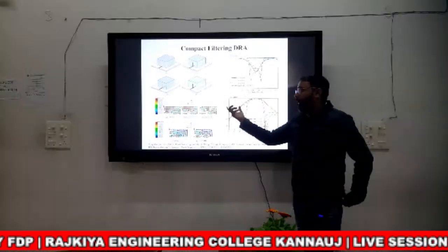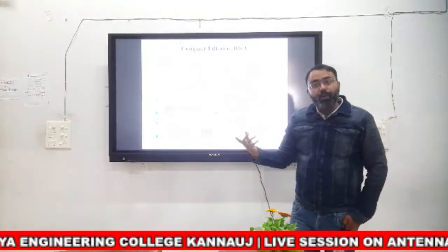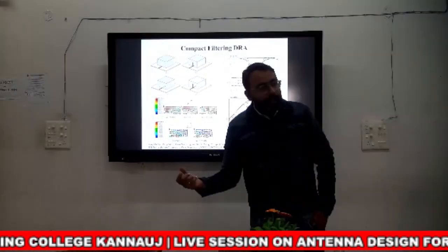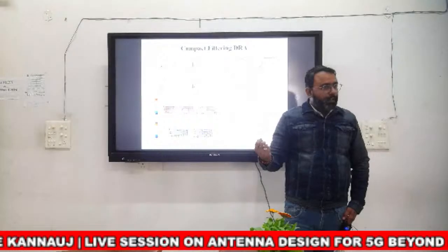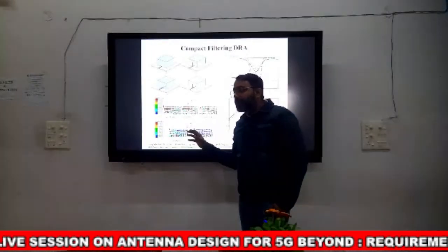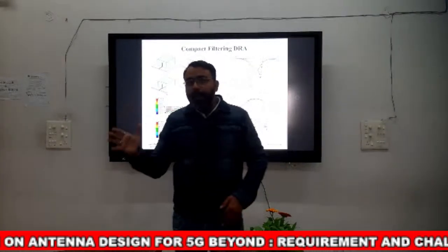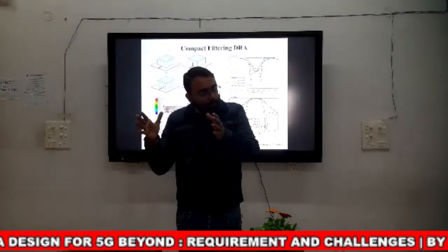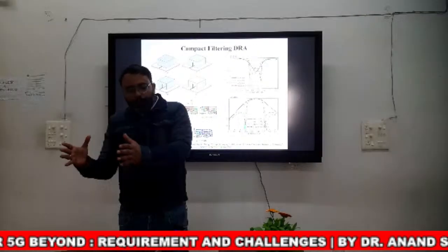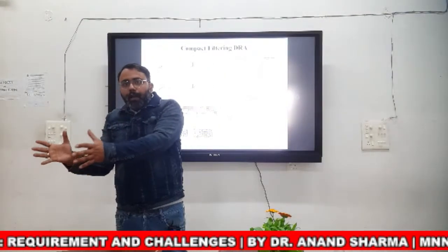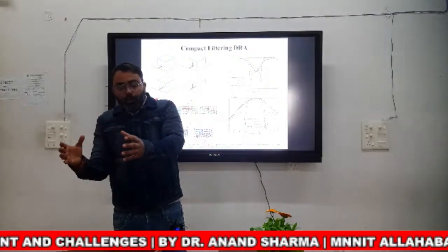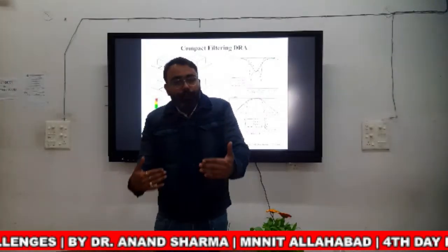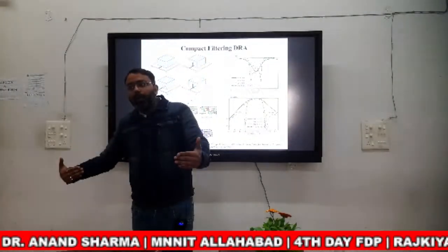So an antenna is a passive device. Why are you using the term gain here? Gain here means you are comparing your radiation pattern with some standard antenna, let us suppose an isotropic antenna. You are comparing the radiation intensity of your antenna with respect to some standard antenna.